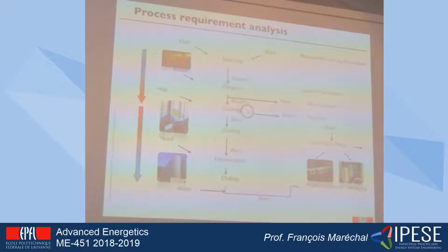In the cooking you do an evaporation and you break the molecules, so you make the sugar accessible to the fermentation. Once you have finished the cooking, then you go to the cooling. Then you cool down, then you add the yeast, and then you do fermentation. After a certain time, you have produced the ethanol, and then you have to stop the reaction. And to stop the reaction, you cool it down to a lower temperature.